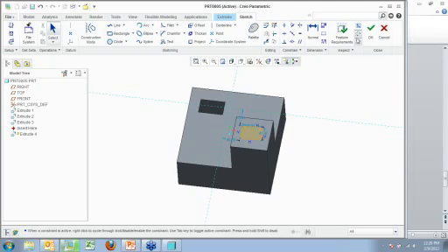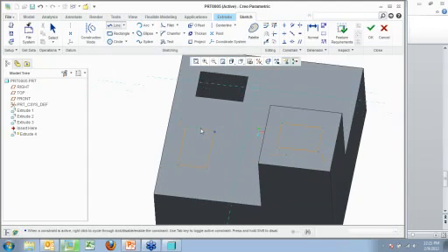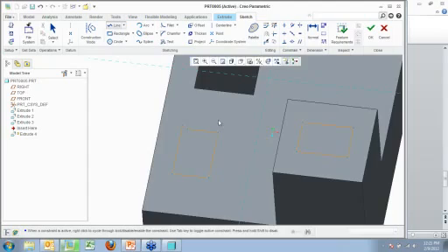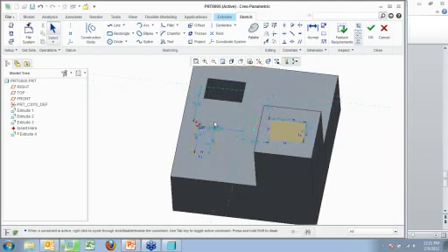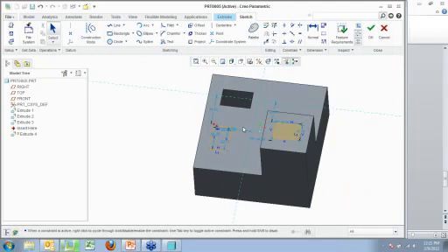So when you're editing a sketch and you change something so that it's no longer closed, let's say I'm sketching a square over here and my ends don't quite mesh up the way I want them to, now you can see it's not shaded because it's not closed, and also it's highlighting the two open ends. And that's really useful when you're editing a lot of geometry, when you're going in and deleting part of a sketch because you want to change the shape of an extrusion or a revolve or what have you.